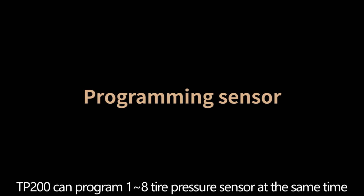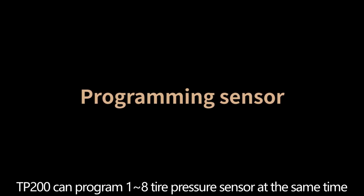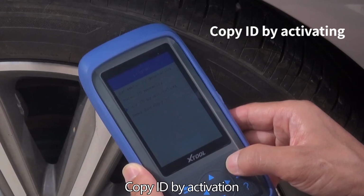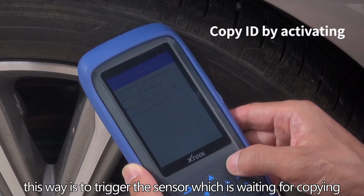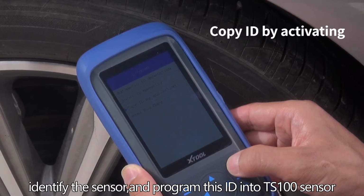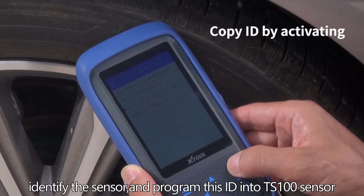TP200 can program 1 to 8 tire pressure sensors at the same time. 4 types of programming methods. Copy ID by activation. This way is to trigger the sensor which is waiting for copying, identify the sensor and program this ID into the TS100 sensor.